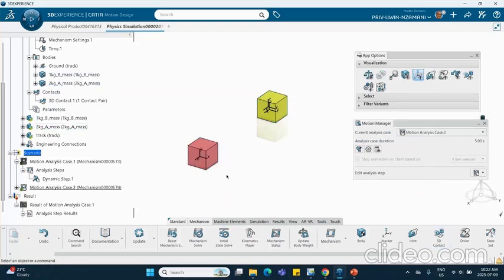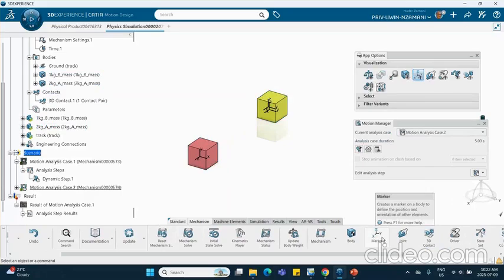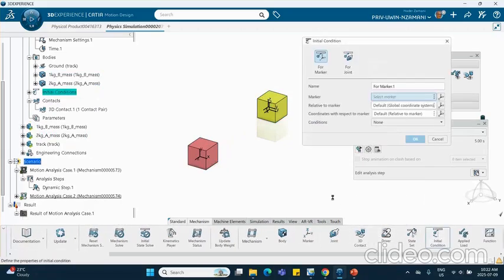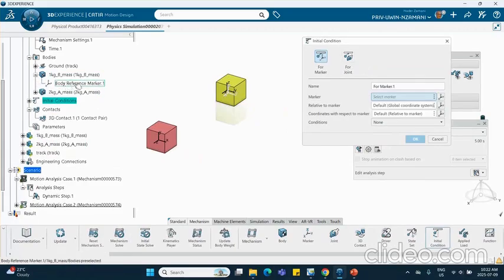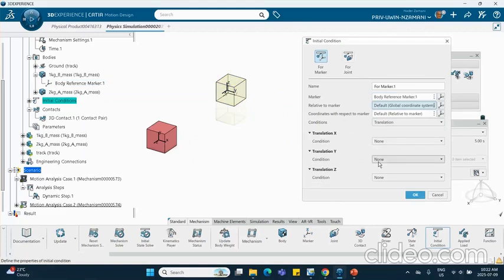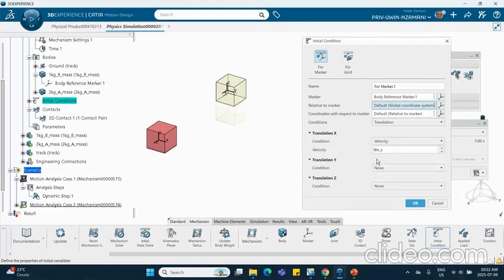All right. Now we want initial conditions, just like before. So we go to initial conditions. Now we cannot do it with joints because there are no joints. So we say with markers. The markers are, for example, for mass 1, here's the marker we selected. Because I don't have any joint, I can't do it with this icon. So now I'm going to say translation, then the x direction velocity, and I can't remember what we did. If we go in the wrong direction, we're going to fix it. So I think this one, we made it -2.